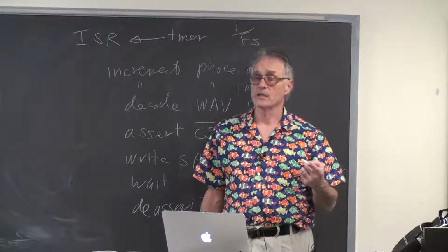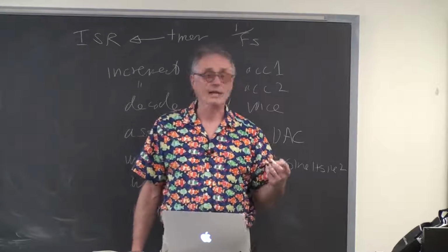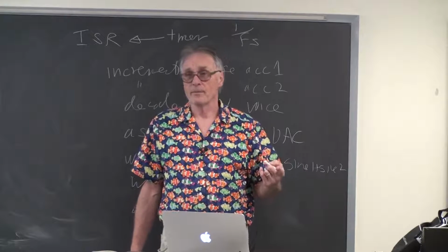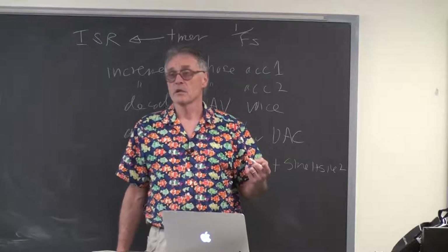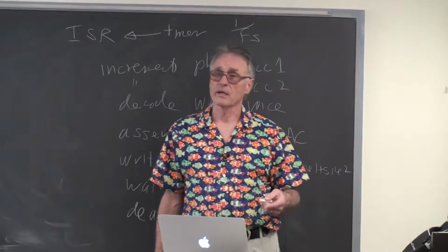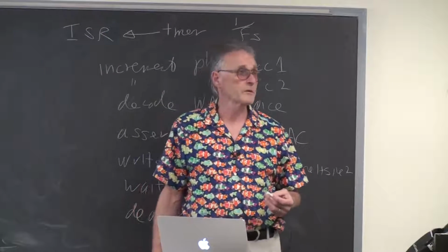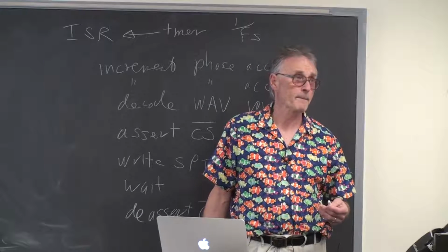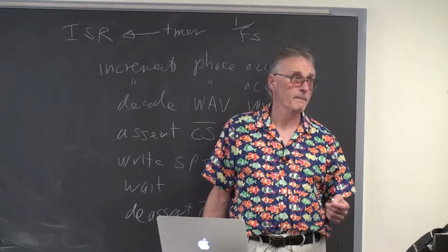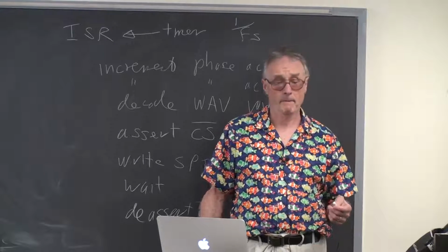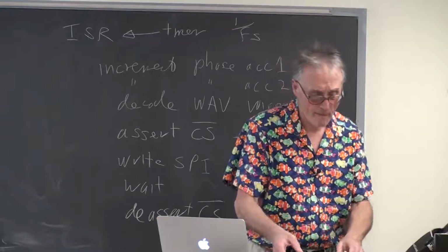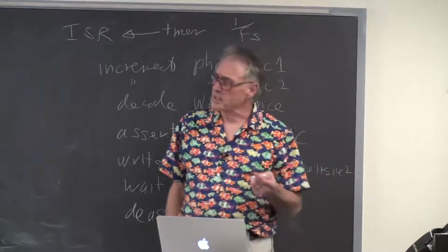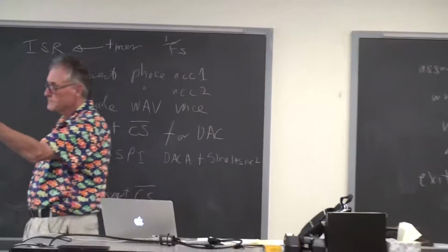In my code I set it to 20 megahertz, which is the practical maximum for this chip. I would actually drop it to 15 megahertz. So it's going to take around a microsecond at 15 megahertz to do 16 bits. Any questions on that?